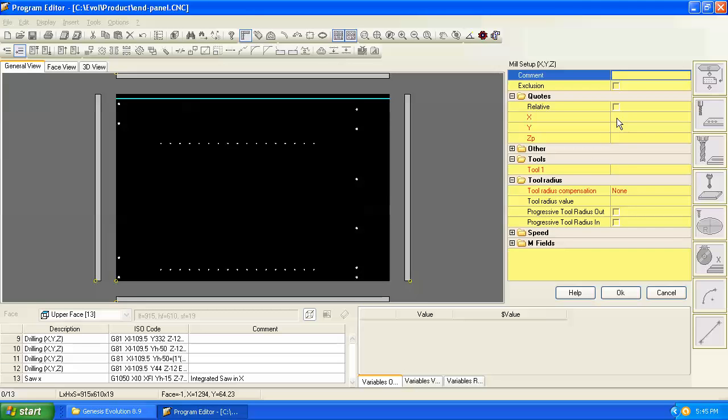So let's start off with the X coordinate, which if we want this to be 100 millimeters off the edge, that's length minus 100. Our Y value, let's start 25 millimeters outside the panel. So we know in our Y coordinate that the bottom edge of the panel here is 0. So if we want to be 25 millimeters outside, that's a value of minus 25.